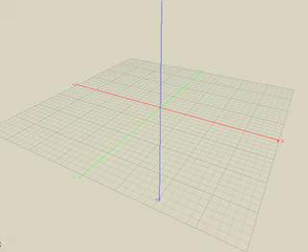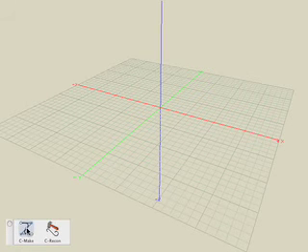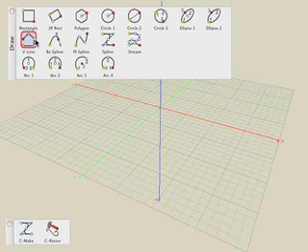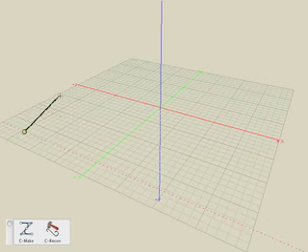Now let's look at the Nurbs curve tools down at the bottom. We have Make Curve, which converts an open and closed vector line into a Nurbs curve, and we have the Reconstruct, which will reconstruct any curve into a new Nurbs curve with new sets of parameters. Before we can use the Make Curve tool, we need an open or closed vector line. So let's go to the Vector Line Drawing tool and create an open vector line.